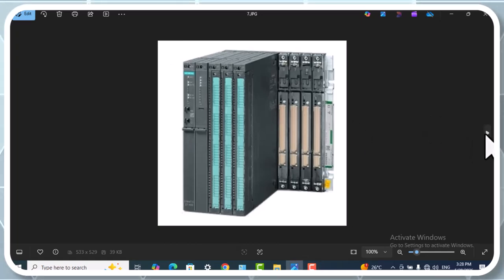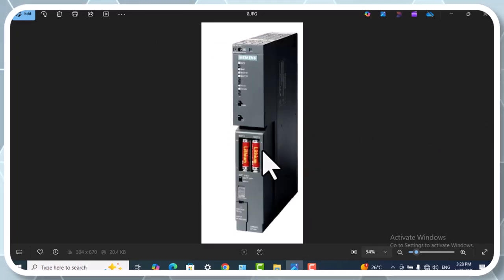And also I want to talk about the battery system. The power supply in the S7-400 can use 1 or 2 backup batteries. Batteries are optional if the program is stored in the ROM, but when the batteries are installed, RAM data is preserved during power failure. RAM data consists of the program, flags, timers and dynamic data, and the CPU real time clock continues working.